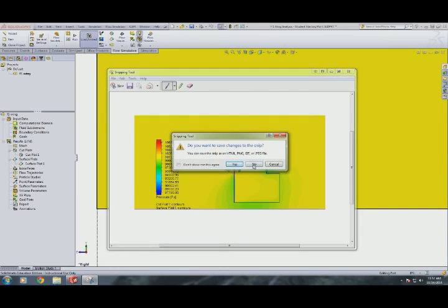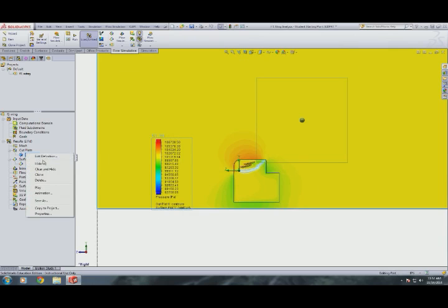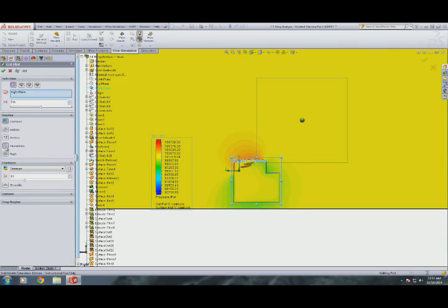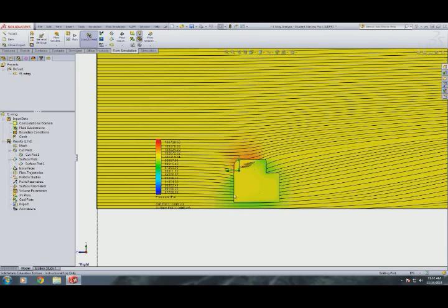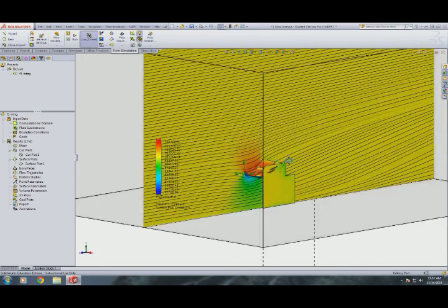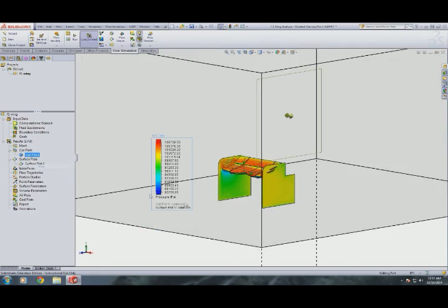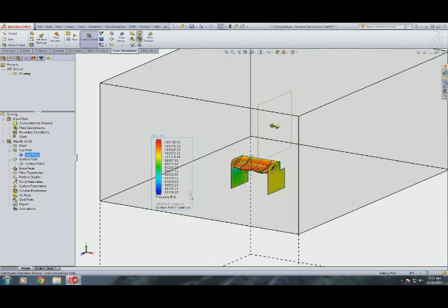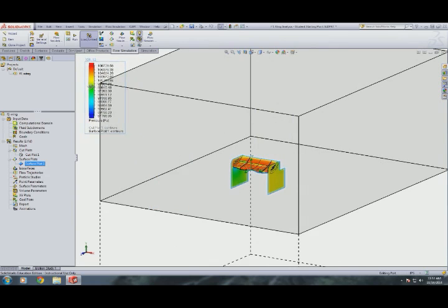I didn't have the streamlines turned on. You just mash this button right there. Now you have streamlines. Properly tuned limits, surface plot showing pressure from 3D viewpoint with flow trajectories. Okay, so to make that image, we need to hide the cut plot. We've already got surfacing turned on. This thing's out of the way. Notice you have to actually click on the little bar to move that around.